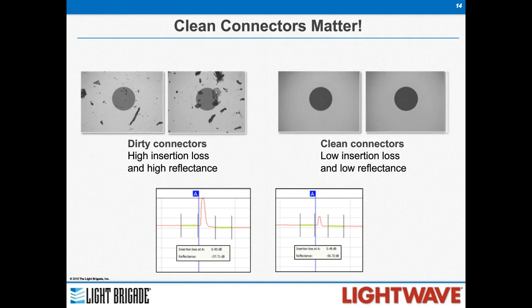So pretty typical spec might be 0.5 dB and a minus 55 or better return loss. So now this pair would have no problem meeting that. Same connectors, simple cleaning. It doesn't take much to get these things to work right if you take care of them.